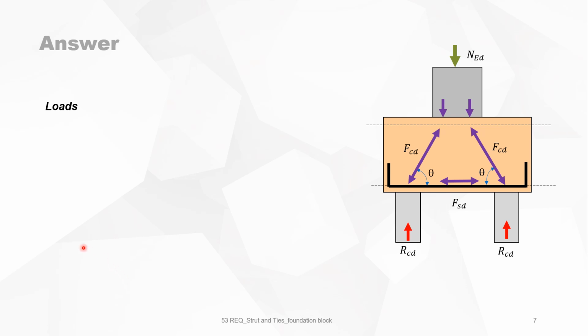So now we will have a look at the loads. The load in ULS is equal to 1.35 the permanent loads plus 1.5 times the mobile loads. And the total load in SLS is, of course, the permanent load plus psi times PM, or 0.3 times the mobile load.